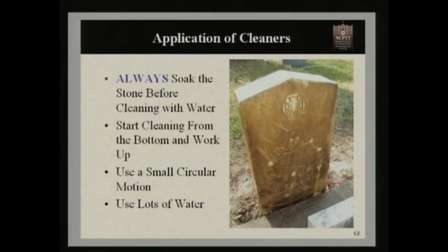It actually saves us time. All the work we're doing stays localized right on the surface, which is where we want to do the cleaning. And also any harmful effects that the cleaner may have, we keep that out of the interior of the stone by having the interior of the stone full of water and keeping that cleaner right on the surface. We want to start cleaning the stone from the bottom and working our way up. This actually minimizes streaking. On a small VA stone like in the photograph, we're not going to see a big difference, but if you work toward larger monuments, you will see a big difference in minimizing streaking and decreasing the amount of work if we actually start from the bottom and work toward the top.